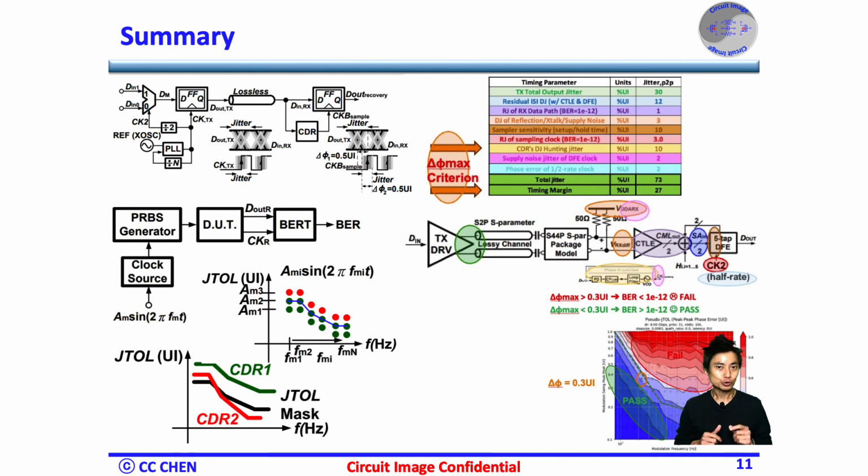With this useful pseudo jitter tolerance, we demonstrate a few images of CDR's parameters, such as loop latency, gain ratio, input pattern, VCO noise, etc., to check the corresponding jitter tolerance sensitivity, such that we could use it as our design trade-off and sign off our design after this jitter tolerance verification. Lastly, I hope this pseudo jitter tolerance can help you to design or verify your CDR efficiently.